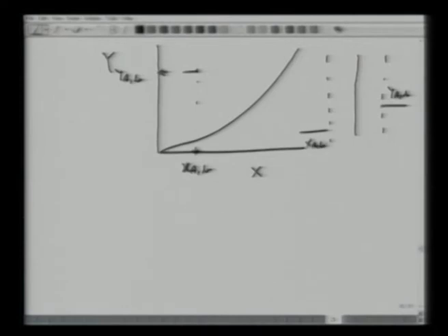Okay, all we do, realizing that the mass transfer coefficient ratio is given in terms of interfacial concentrations YAI and XAI, we can take a slope of minus Kx over Ky, because Kx over Ky has been shown in terms of YAB, XAB and YAI and XAI.